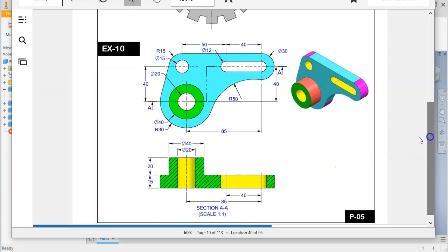You'll notice that the A and the A are not on the same horizontal plane like in one of the last video lessons where you learned how to make a section view. It's actually going halfway through the part, then downwards, and then finishing out past the part. So imagine using a laser cutting machine to cut through this part, or even a saw. You would cut through this line, go down, and then cut through this line. That will produce section AA, which you see here.